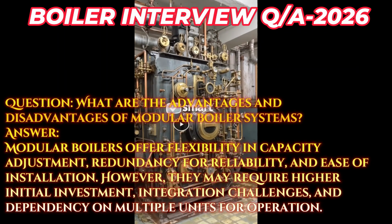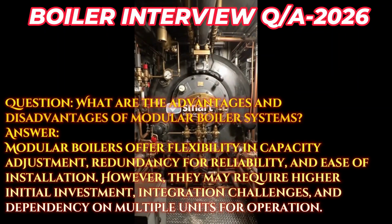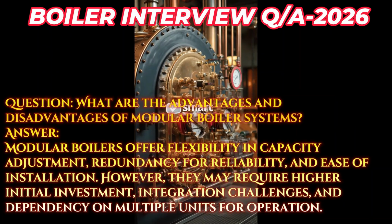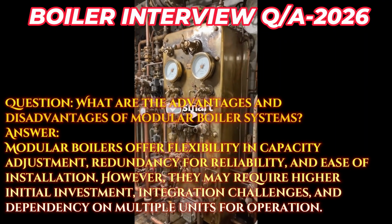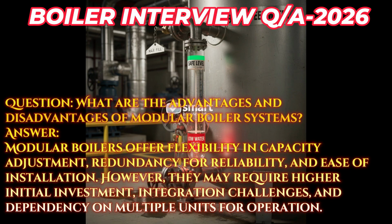Question. What are the advantages and disadvantages of modular boiler systems? Answer. Modular boilers offer flexibility in capacity adjustment, redundancy for reliability, and ease of installation. However, they may require higher initial investment, integration challenges, and dependency on multiple units for operation.